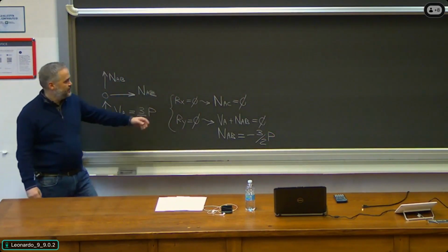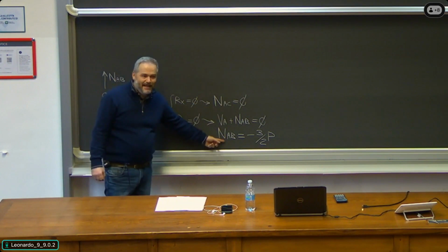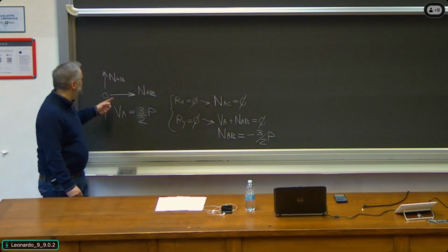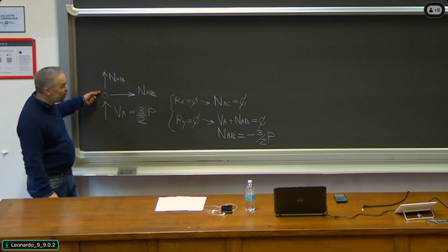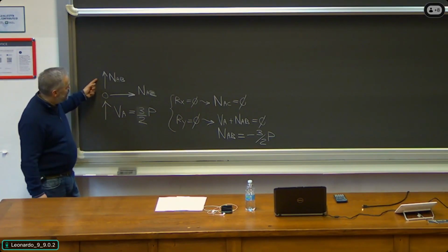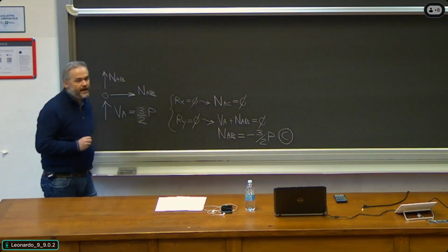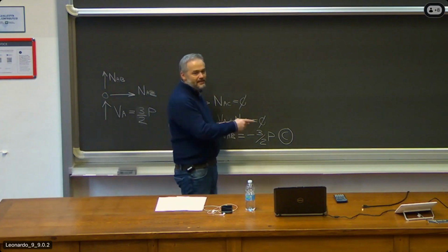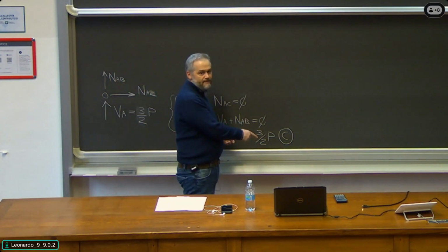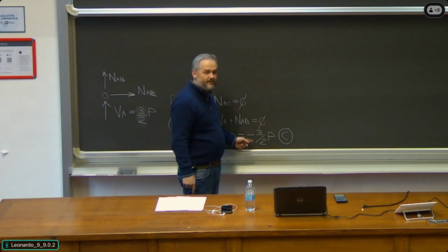Look at the results. For the zero, we have no doubts about it. We don't have to specify whether it's tension or compression. It's simply unloaded. This is a negative result. I assumed it to be tension. Drawing it like this on the node means it's tension because it pulls. If I have a negative value, it means this is compression. Okay? This is the way to clearly indicate it. By writing this C here, I know that regardless of the sign here, it's compression.